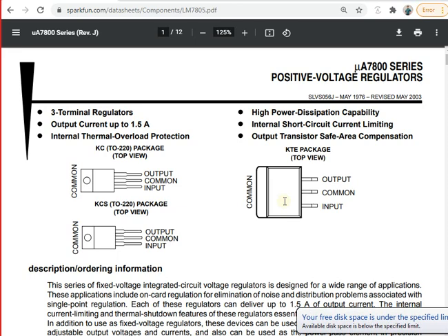And now even, I guess, those who are iPhone fans must have an idea that they are reducing their power consumption, and their battery is now a lot improved from their previous series. The reason is this, that now they are not working at 3.3 volts, they are now working at 1.2 volts or 1.8 volts. What does this mean? A binary 1 is actually taken as 1.8 volts, and binary 0 is taken as something like 0.0 or 0.1 or 0.2. So this difference is actually decreasing, so you have less voltage, you have less current flowing over there.